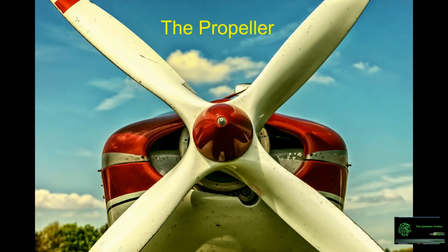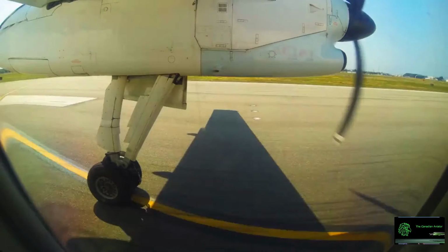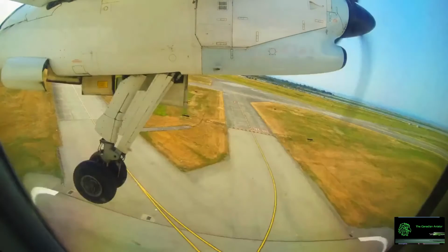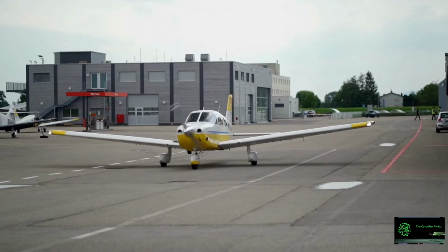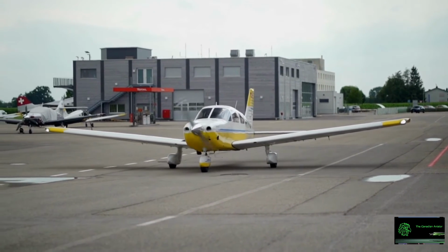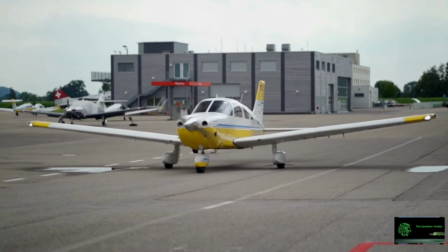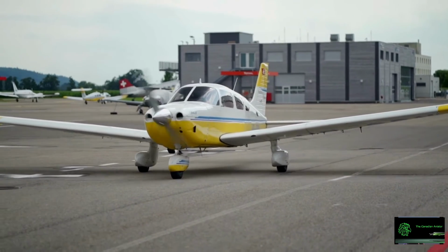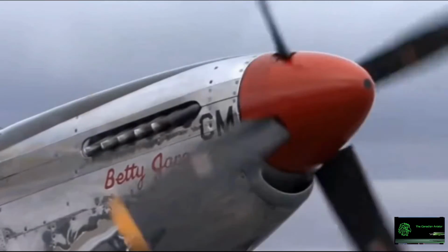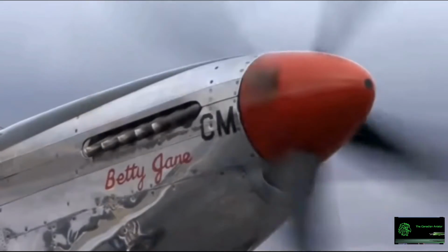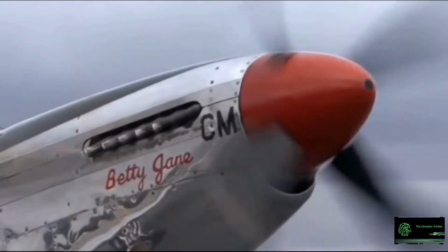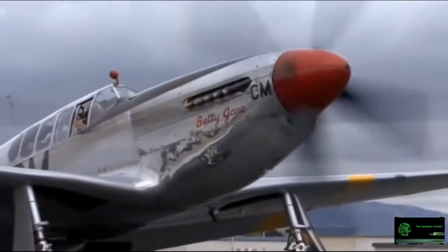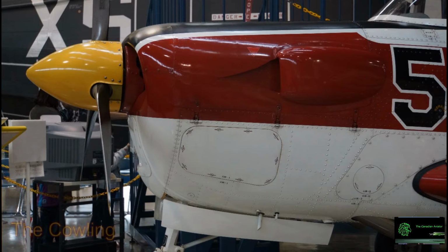The propeller. The propeller provides a certain propulsive force to the aircraft according to the number of blades, engine power, and many other factors. Blades of equal length meet at the center hub attached to the crankshaft of the aircraft engine. Therefore, engine power is transformed into the mechanical energy needed to rotate the propeller. On a medium-sized propeller, the centrifugal force pulling the blades to lift the hub may range from 40 to 50 tons per blade.